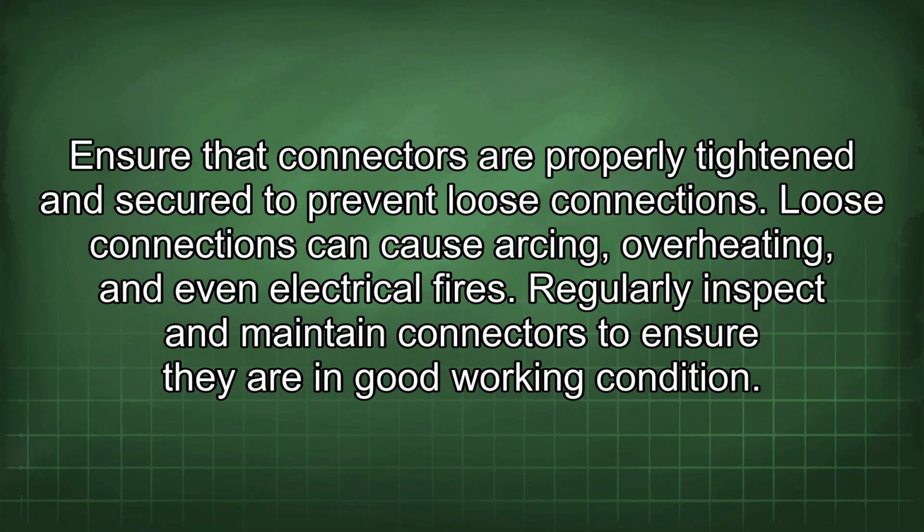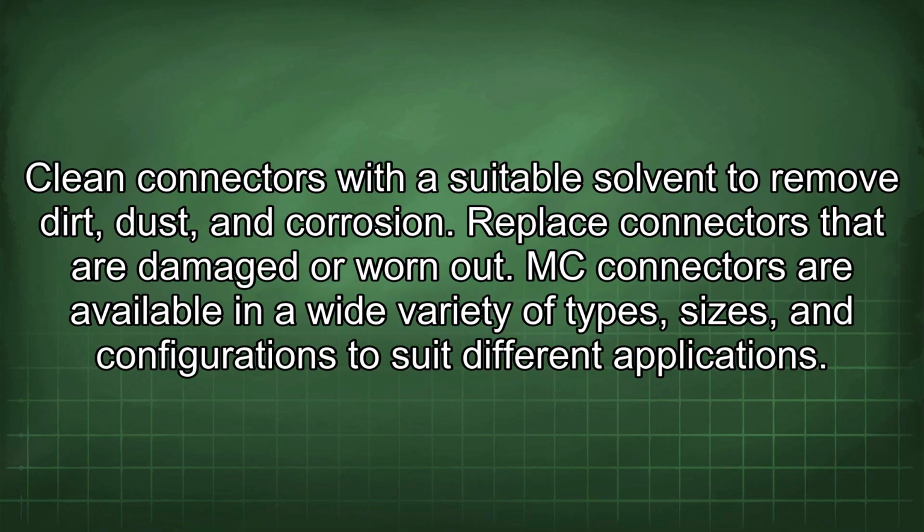Ensure that connectors are properly tightened and secured to prevent loose connections. Loose connections can cause arcing, overheating, and even electrical fires. Regularly inspect and maintain connectors to ensure they are in good working condition. Clean connectors with a suitable solvent to remove dirt, dust, and corrosion. Replace connectors that are damaged or worn out.